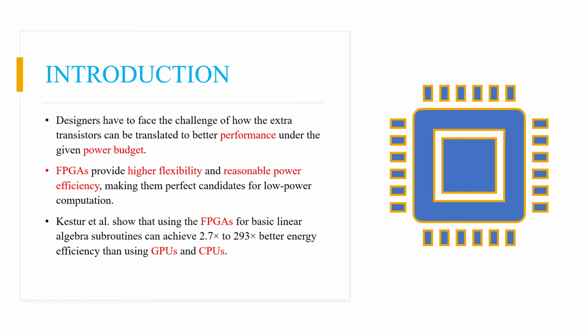Their experimental results show that, compared with the CPU, the accelerators on the FPGA layer can reduce function-level power and EDP by 6.9 and 7.2 times, respectively, and application-level power and EDP by 1.9 and 2.2 times, respectively, while delivering similar performance compared with a baseline system consisting of a CPU layer and a DRAM layer.